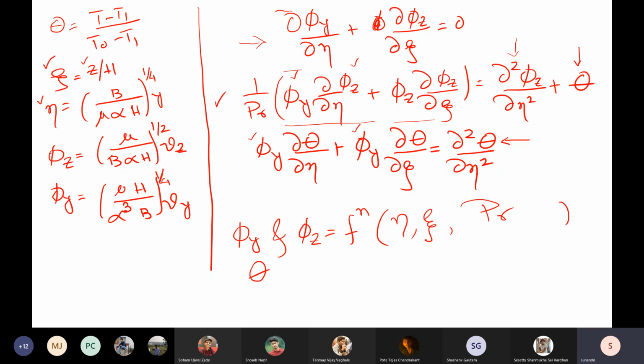If you set the convection component of momentum transfer equal to 0, what kind of a flow is that? It is called creeping flow. So in creeping flow, you do not have any contribution from the left-hand side of the equations of change, principally the equations of motion, and that's why it's called creeping flow.